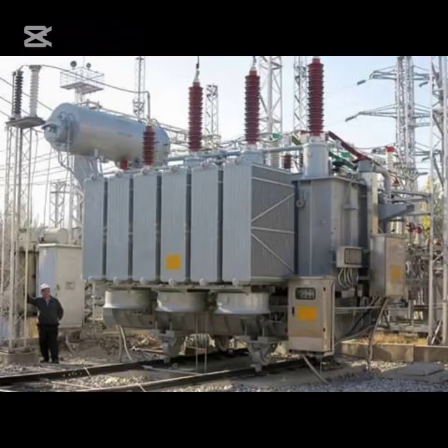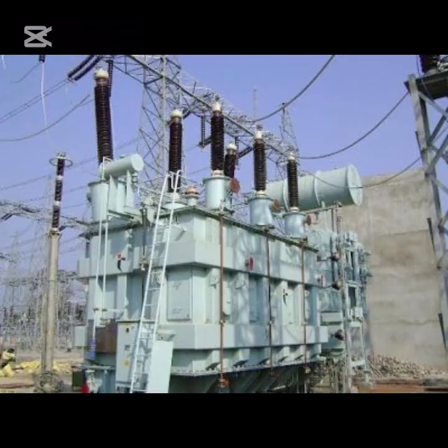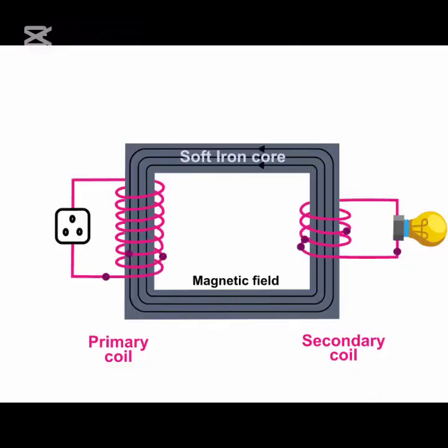2. How can we know if a transformer is step up or step down? Before I continue, a step-up transformer means that the secondary voltage level is higher than the primary side, and step down means that the secondary voltage level is lower than the primary side. Know that the primary winding is the input, and the secondary winding is the output, or load side. Looking at step-down transformer coils carefully, it will be noticed that the number of windings in the secondary winding of the transformer is lower than the primary winding.